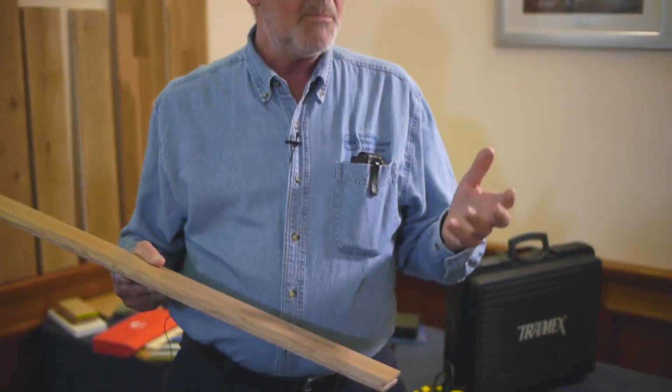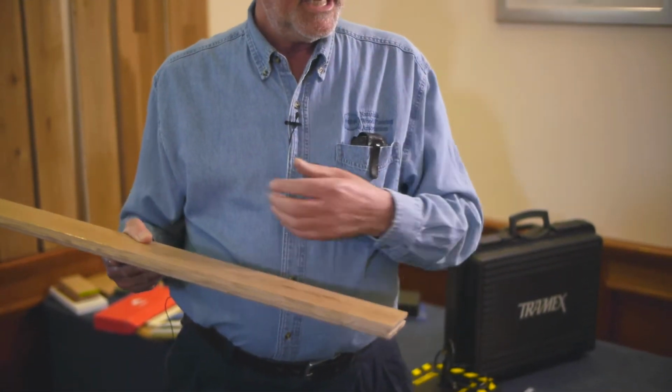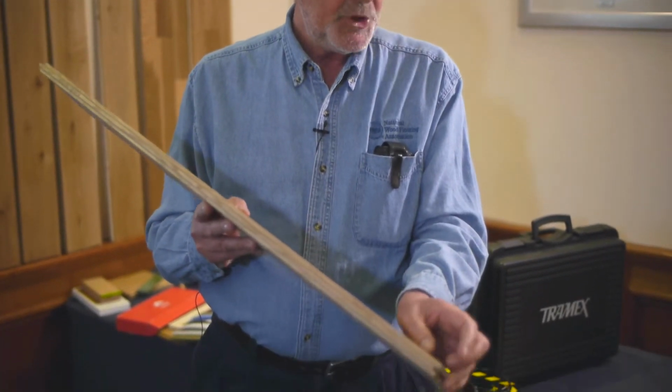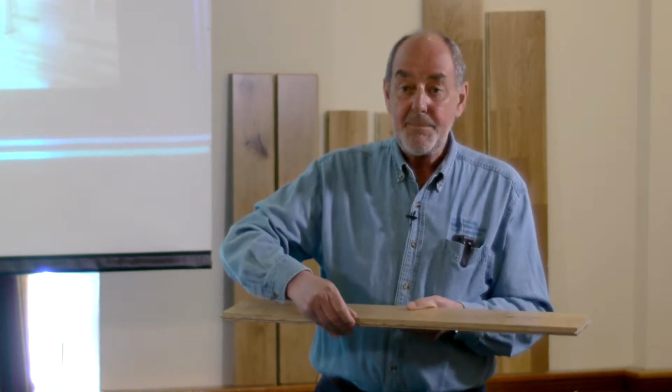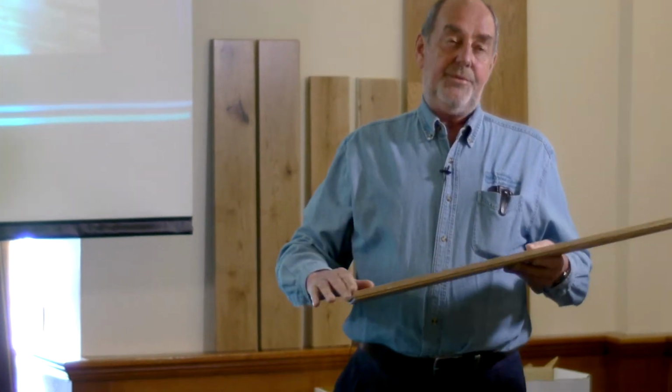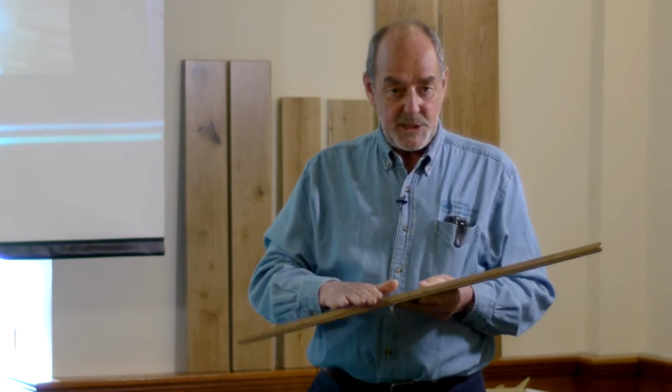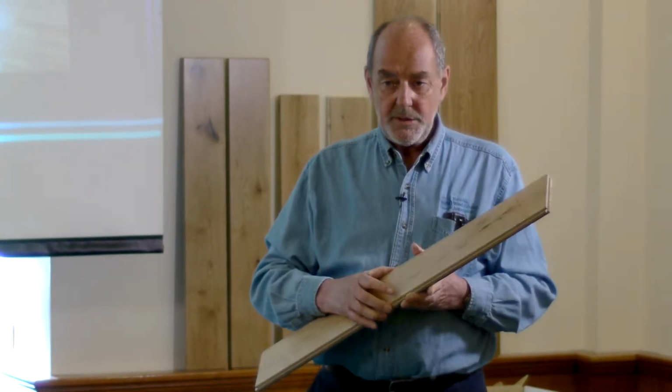It's to disguise unevenness in boards. Boards now are manufactured at high speed, and the accuracy is less than perfect. So by putting a small chamfer here, you don't get a lip. You would have a lip on the edge, the end, between it and the next board. So you disguise the fit by putting a small chamfer. Then you don't get a tiny lip between this and its neighbor, here or here. And that's necessary with 90% of pre-finished wood flooring. There's one exception, maybe you know it, Bruce.